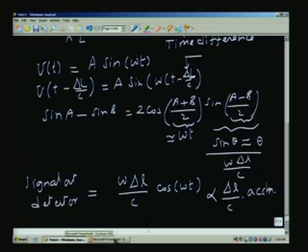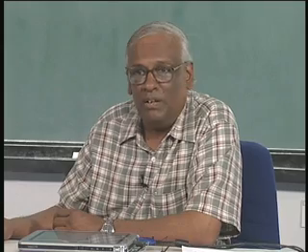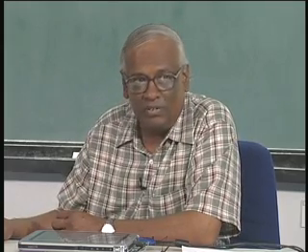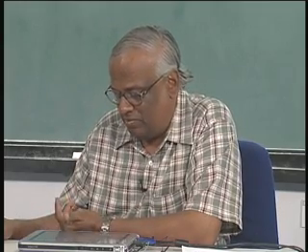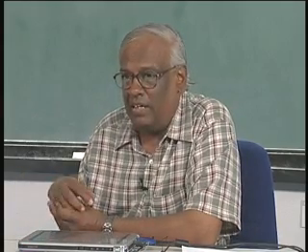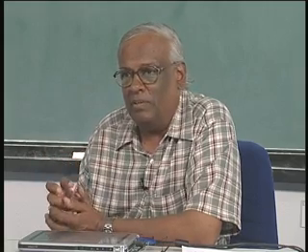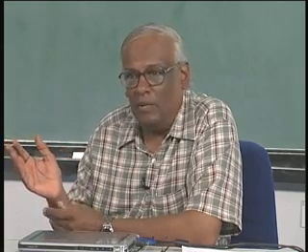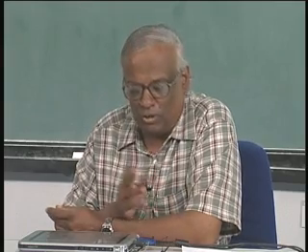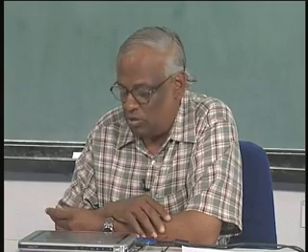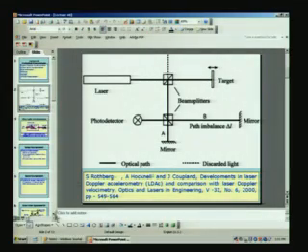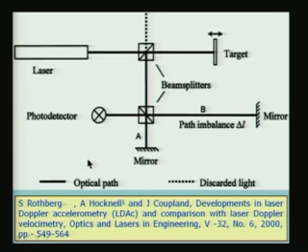So, that is one type of instrument which we can think of, where we are using the vibration to generate the acceleration signal through the optical mixing of two beams by introducing a certain delta L path difference. And this path difference can be introduced nowadays in a simple way, by taking a coil of optical fiber, and the length can be suitably adjusted, so that you get a sizable factor delta L by C, and therefore, we can do that very easily. The light passes through the optical fiber, goes to the other end, gets reflected from the mirror, comes back through the same fiber, and then is mixed with the other beam. The two beams can be mixed together with a large path length required. Delta L can be large, because C is a very large quantity. So, that is one way of measuring the vibration or the vibration acceleration.